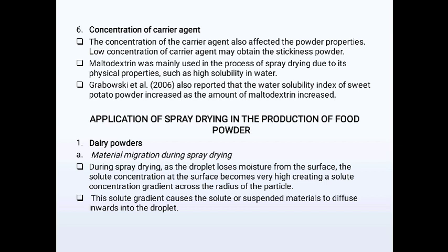Concentration of carrier agent. The concentration of the carrier agent also affected the powder properties. Low concentration of carrier agent may result in a sticky powder. Maltodextrin was mainly used in the process of spray drying due to its physical properties such as high solubility in water.